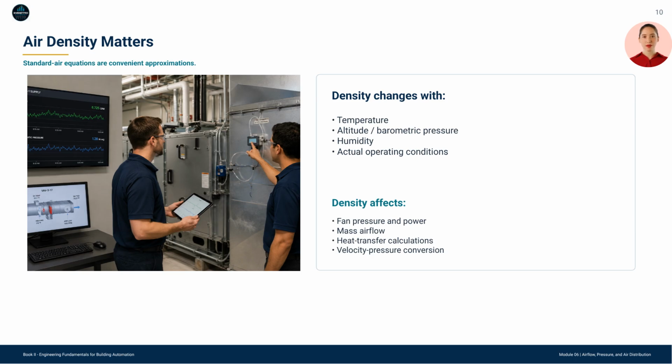If you are comparing measured airflow, calculated load, fan pressure, and energy use, make sure you understand whether the values are based on standard conditions or actual conditions. A BAS professional does not need to overcomplicate every calculation, but they must know the assumptions.